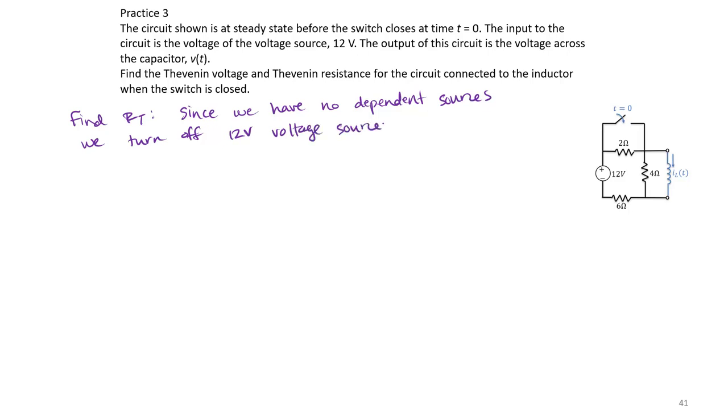Remember, voltage sources are replaced with shorts, current sources are replaced with opens. And we get something like this.